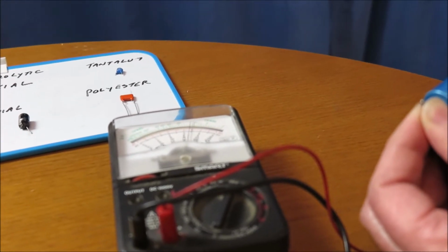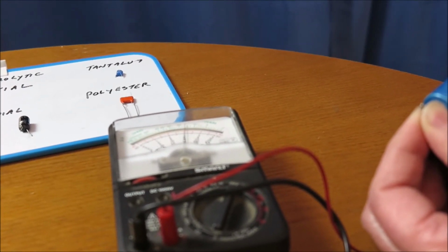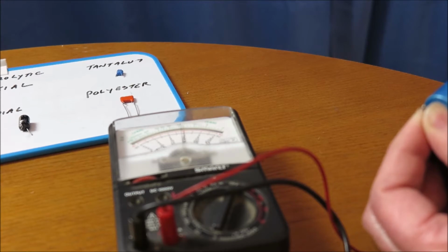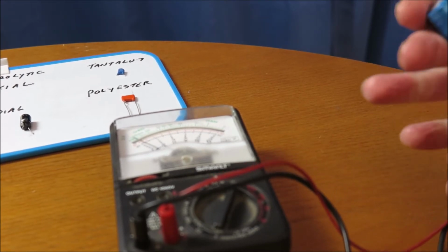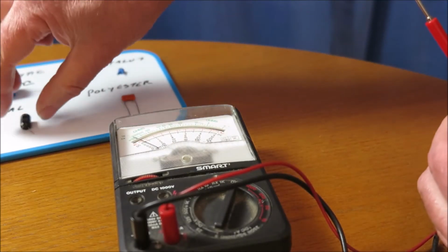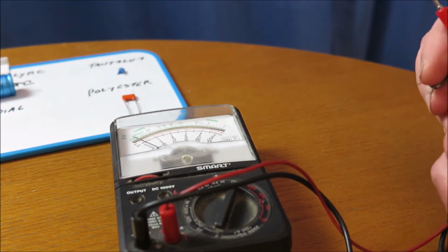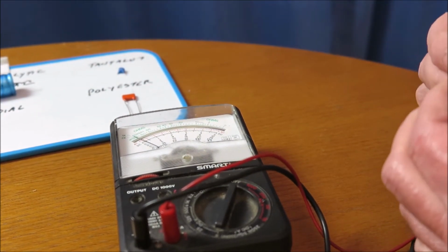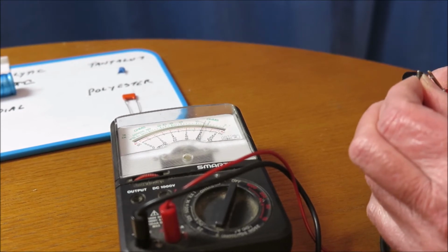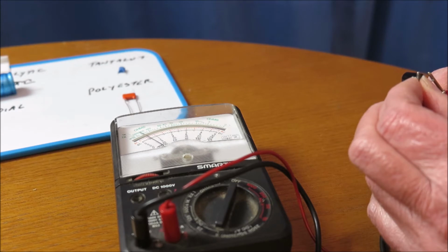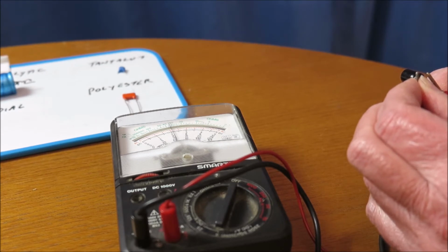This is measuring resistance, so it's passing a tiny current, and you can see as the capacitor is charging up, the current is diminishing. So you can see the capacitor slowly charging, and you can use that for a capacitor test as well. And now the radial capacitor we have here, that's a lot smaller value of farads, so if we connect that, what we should see is a very much quicker charge, because there's less capacitance to charge, and you can see that going down quite quickly as the capacitor is charging up.